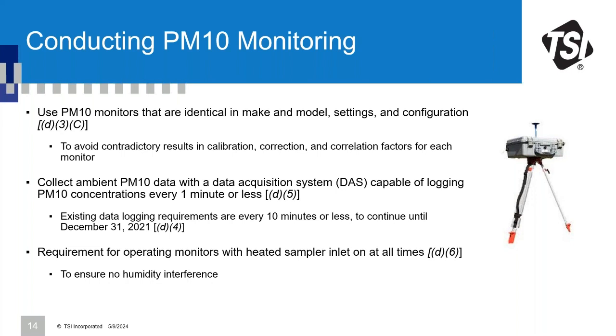So for PM10 monitors, one thing that South Coast has brought in with its new amendments is to make sure that the device is factory calibrated, but also reading within a certain plus or minus to another PM10 device. So there is a component to that as well.